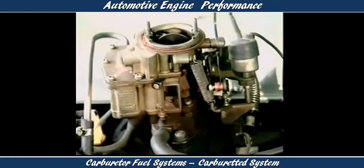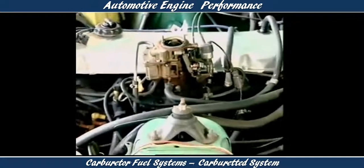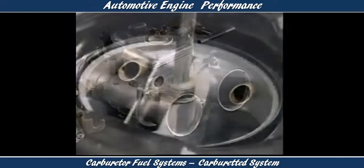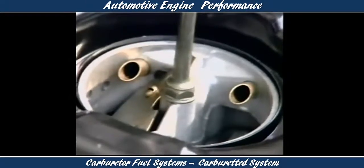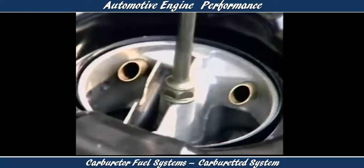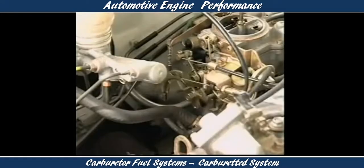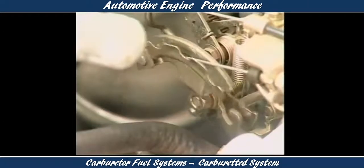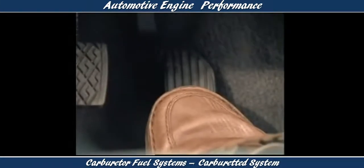The downdraft carburetor is the most common kind. It's mounted on the intake manifold. The side draft model is less common. The carburetor turns liquid fuel into a fine spray and mixes it with air. It also controls how much air-fuel mixture is delivered to the engine. This is done by the throttle valve near the bottom of the carburetor, which is connected to the accelerator pedal.